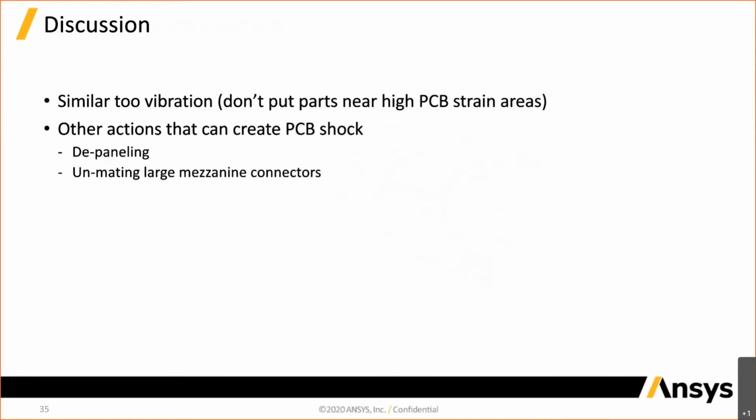And it ended up during tests, they would put the board down on a test board, and when they pulled it up is when they were actually breaking it. It was the unmating of the connector. It was a really large board-to-board connector with a lot of pins, a lot of force, and they were very careful pushing it down because they wanted to make sure everything was even as far as force goes. But when they were pulling it up, they didn't make the same consideration. So the board actually was failing after they unmated it, where it would snap and cause the BGA balls to break.